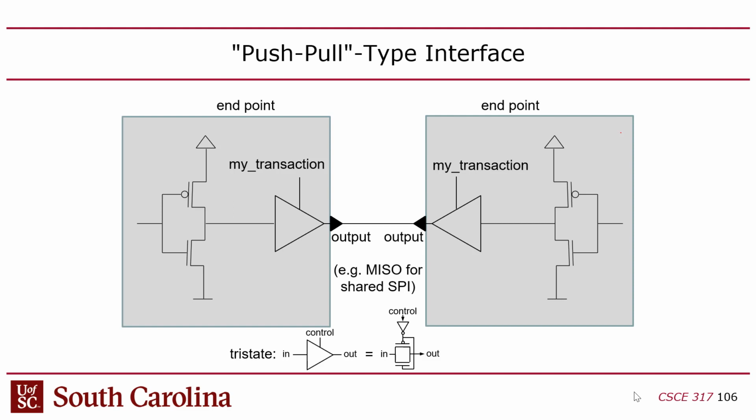But you have to be careful that there are no misunderstandings when you run your system. You've got to make sure that you don't have more than one connected, non-tri-stated bus on there. But if you have a tri-state bus, then you effectively get a third logic level, which is don't care, or Z. So you could put a 0, 1, or Z. Everyone with me? Okay.